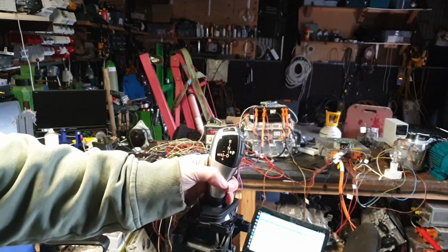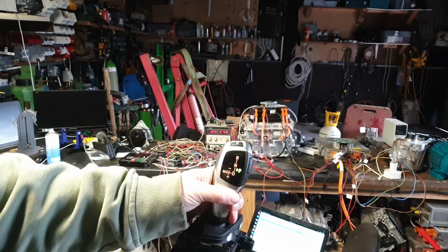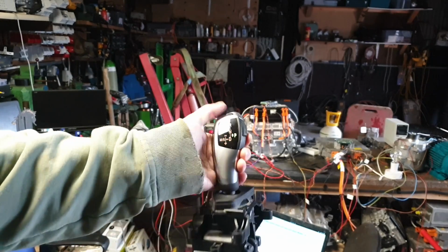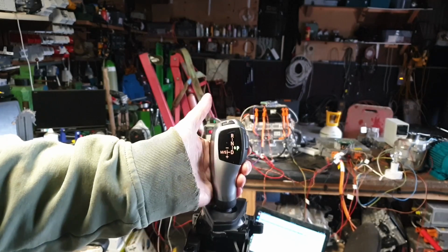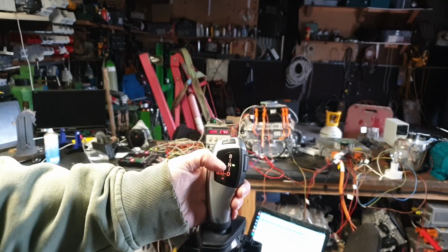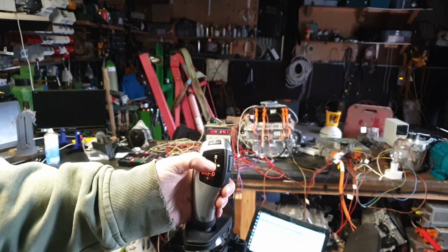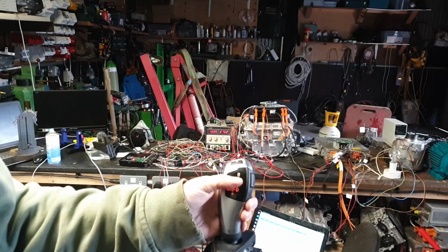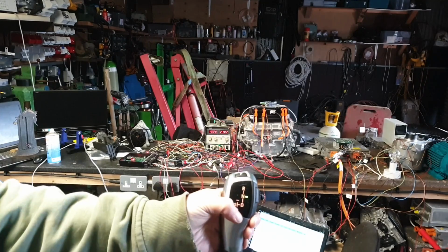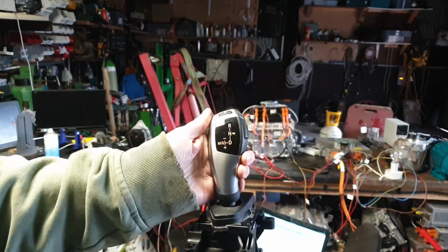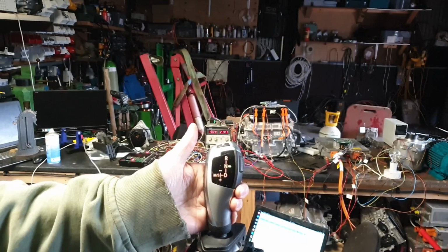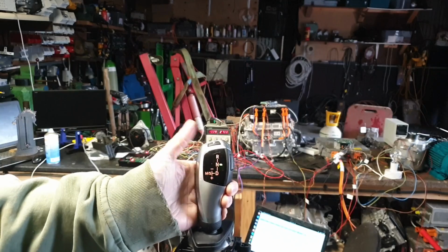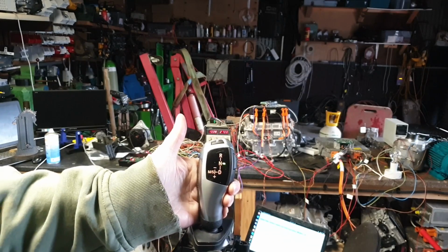Now at the minute, this park function is basically the same in the VCU as neutral, it just zeroes out all torque requests. So the usefulness of this isn't there at the minute. It will be when we're controlling certain gearboxes and drivetrains that have an electronic park facility in them.